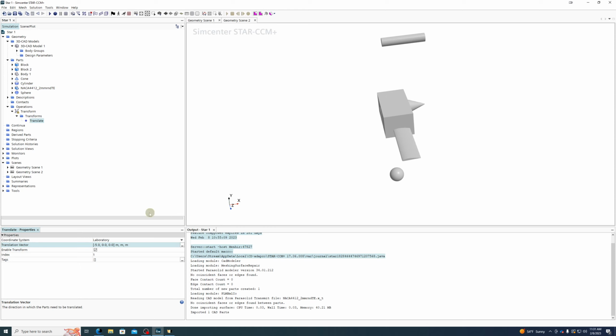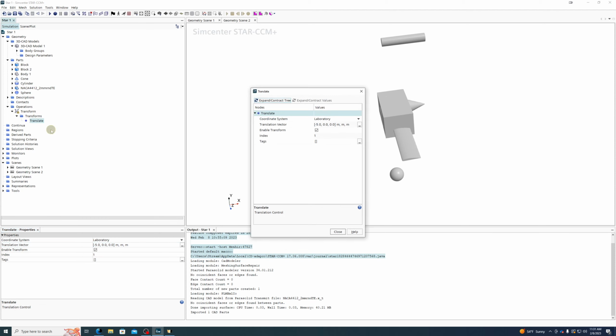This is one of the reasons this property window is so useful, because you can just change numbers directly from here. You could also right click and hit edit. That works too. It'll bring up a menu where it'll tell you what direction I'm transforming this in, and by how much. You can click on any of these numbers, and you don't have to type it in as shown here. You can just type in 3 numbers with spaces in between them. So you can type in 0 space 0 space 10, and it'll convert that to this vector format.